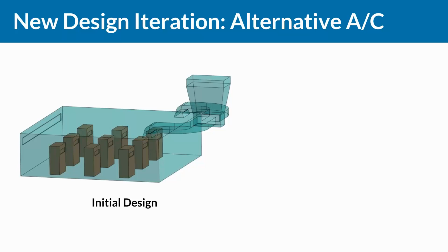Based on what we have seen, the flow has been stopped by this first computer over here, and that's why the cold air cannot go to the other heat sources, and that's why we have this problem of non-homogeneous distribution all over our heat sources. Of course, this is this case, but if you are doing another application, the decision can change, depending on the objectives that we are looking for.